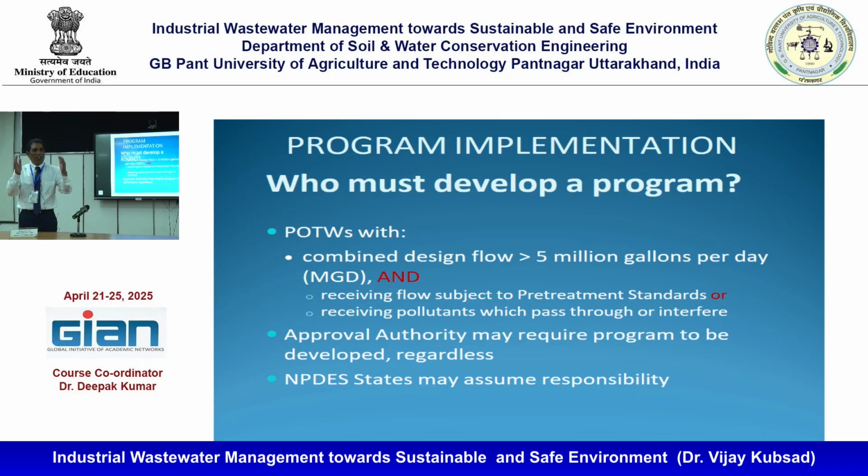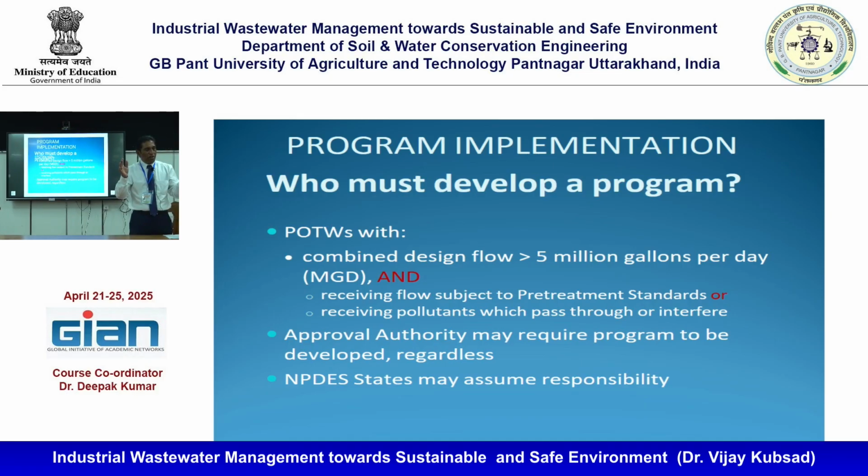If a city designs a treatment plant, you cannot overload it with industrial wastewater only, because it is basically built for the residential wastewater. But in the biological system, if you have a 5 million gallon wastewater treatment plant, you can accept about 10%, 20% of industrial wastewater also. Make it compatible and treat them. So that is how they need not worry.